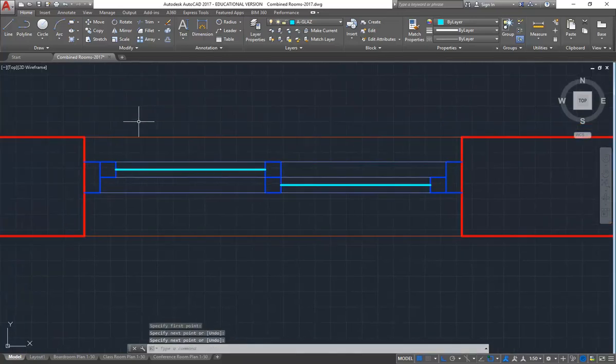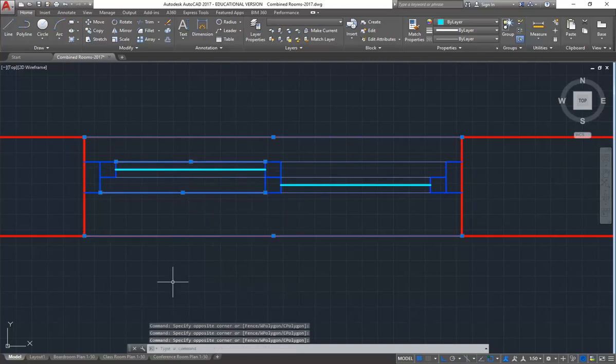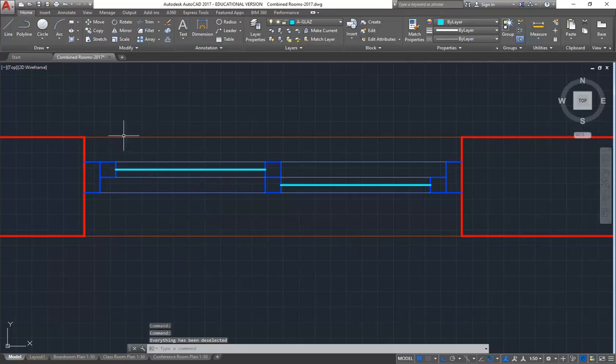Okay, but can you see how much better that reads than what you've got on this floor plan? Because these parts here have lighter line weights, and the only way you can achieve that is by having separate lines. You can't have different line weights for a single line. So that's really all I wanted to show you, that you can break these lines up, and usually the best way is to trim the openings first.